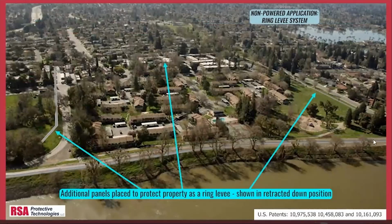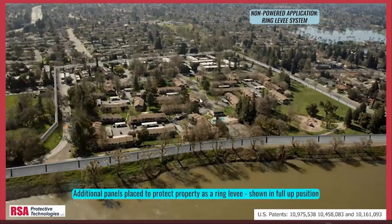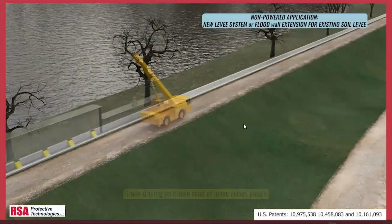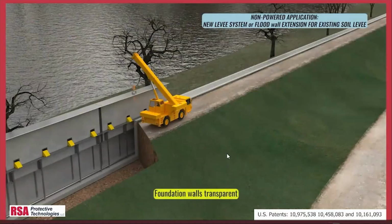In areas where the levee is localized, but floodwater could continue all the way around, this is a system called a ring levee, where you can protect the entire perimeter of a community or an industrial section, in order to avoid getting water coming in from the backside. This shows the wall at the top of the levee being raised up by the crane. You see the cutaway there shows the foundation down inside the levee.